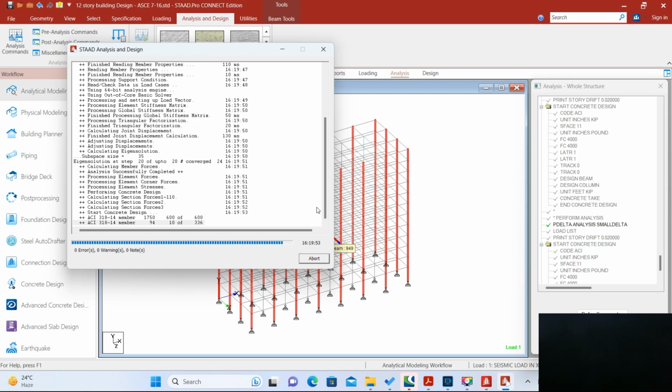So, the big lesson learned is that whatever practice we have been following in Pakistan and designing the building as per Building Code of Pakistan of 2007 version, which was based on UBC 97, we end up with thin columns.